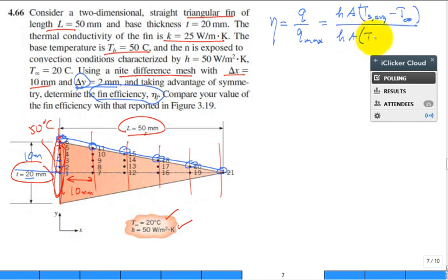Okay, how about the maximum? HA, guess what? This average surface temperature, if I have infinitely high thermal conductivity, then everywhere on the surface of the fin is the base temperature, TB minus T infinity. So I can calculate it getting rid of those same areas, same H's. It's really this average surface temperature along here versus the base temperature. So it boils down to, if I want to calculate this fin efficiency numerically, I need the surface average temperature.